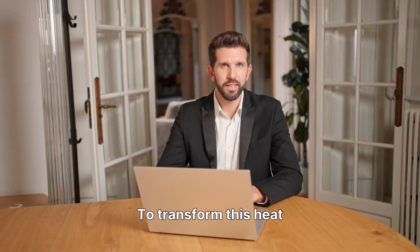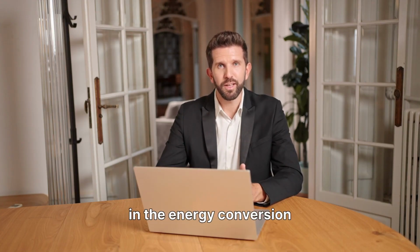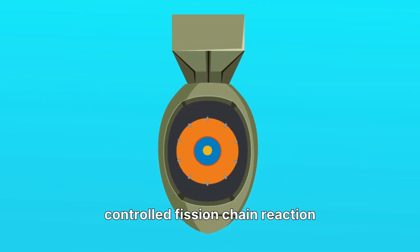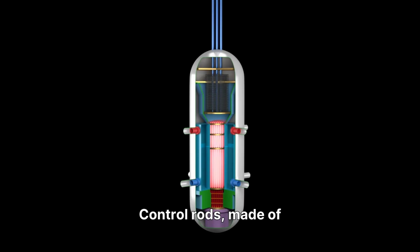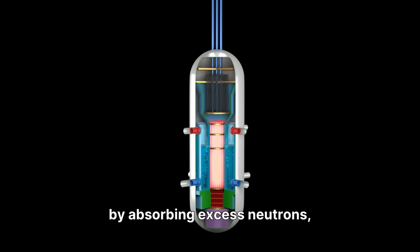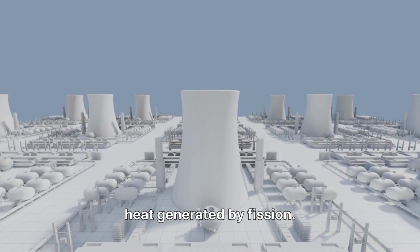To transform this heat into usable electricity, a nuclear power plant incorporates several crucial components, each playing a vital role in the energy conversion process. At the heart of the plant is the nuclear reactor, where the controlled fission chain reaction takes place. Inside, fuel rods containing uranium are carefully arranged. Control rods, made of neutron-absorbing materials, are used to regulate the reaction by absorbing excess neutrons, preventing the chain reaction from becoming uncontrolled. A coolant, often water, circulates through the reactor core, absorbing the immense heat generated by fission.